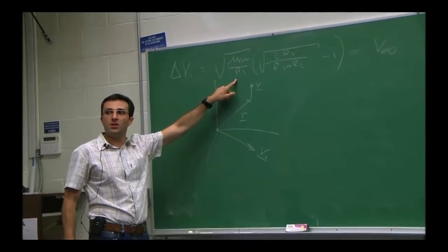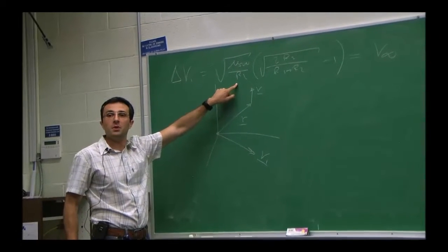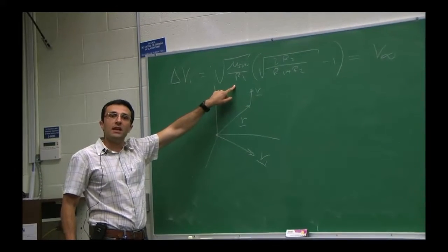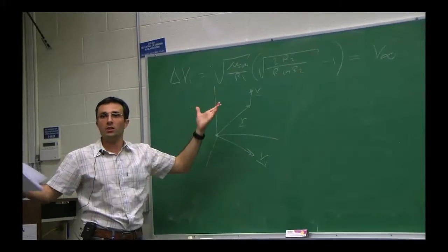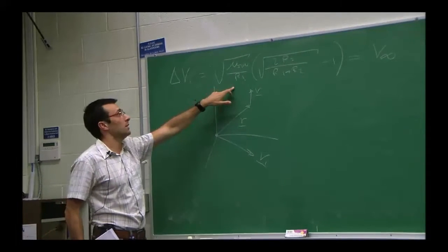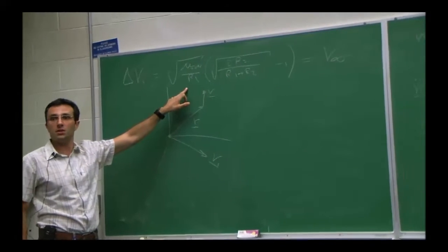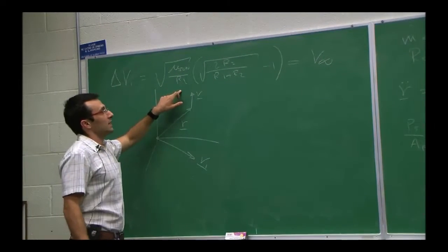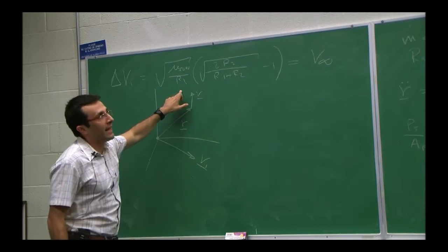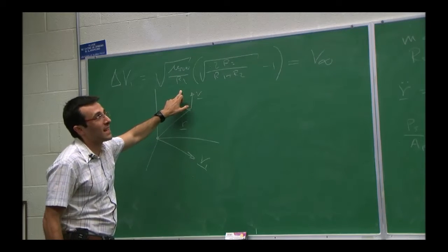So this is the patching between the conics, really. It's this point right here. What I've done up to this point is just Hohmann transfers between a circle and a bigger circle. And you can compute the delta V's, right? And this is one of them. This is to leave the smaller circle and go on the big one, right? And go on the cruise trajectory. So this is the first delta V. Well, how do I connect that to what happens inside the sphere of influence?